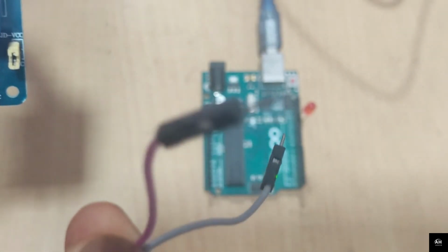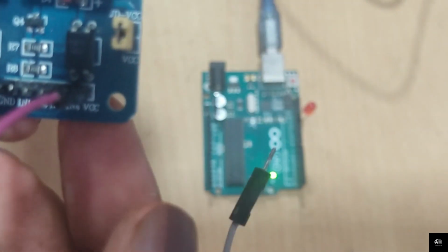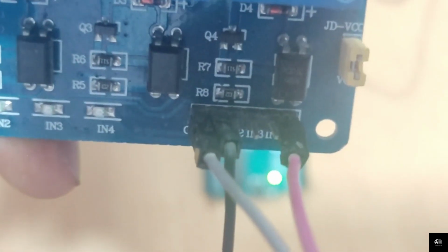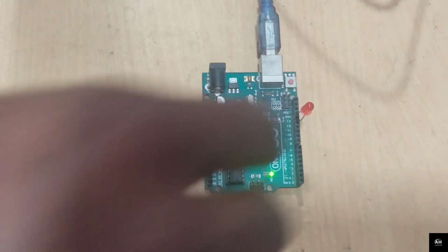So now I have connected these 2 wires here, and here are the other 2 ends of it. We will be connecting these 2 ends, one will go to the ground and the second one will go to the 5V on the Arduino board. And we will also be connecting another GPIO pin with the pin 12 on the Arduino board. So let me get another wire. I will be connecting it on the IN1 on the relay module. You can see here I've connected it successfully, and we will connect these wires onto our Arduino board.